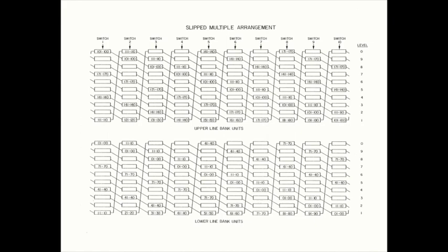With the multipling arrangement, it follows that each of these line circuits will also have one appearance on level 2 and level 3 and level 4 and so on all the way up to level 0. This multipling arrangement is exactly duplicated in the middle tier for line circuits 100 to 199, and then the whole multipling arrangement is exactly duplicated on the upper shelf for line finders 11 to 20. We'll see how this multiple slip arrangement helps to minimize switch wear and provide equitable service levels after we look at the line finder selection sequence process.